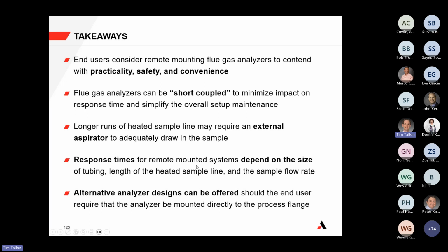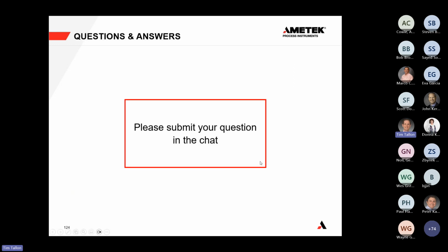For response times, it really depends on everything we talked about: the length of the tubing, the size of the tubing, and the flow rate. And then, for alternative designs, really got to be creative and thoughtful as to how we can mount it directly to the process. So I do see that there are some other questions.